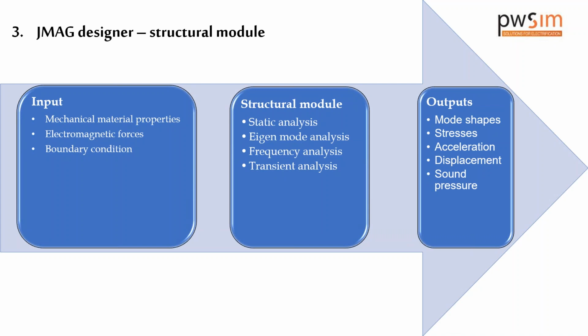So this structural module will give an analysis of how the stator is getting deformed when forces are acting upon the motor, how the rotor is deforming, how the eccentricity is caused, and what type of forces are produced by the motor, like the radial forces and the tangential forces. All these things can be calculated using the structural module.